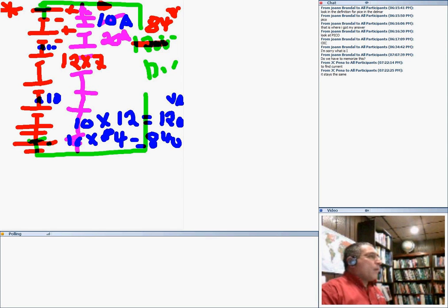If you need more power, you add another string in parallel. Can you guys see that, another string in parallel? Each string will give 10 amps. The two together will get you 20. They add up, and you double the amount of power. So that's you, my friend, if you need more power and you need to continue the same voltage. I love that 84. I don't want to change the 84. No problem. Just add another string in parallel. Can you guys see how they're tied here at the top together? Any questions before I move into the second application of a series circuit?